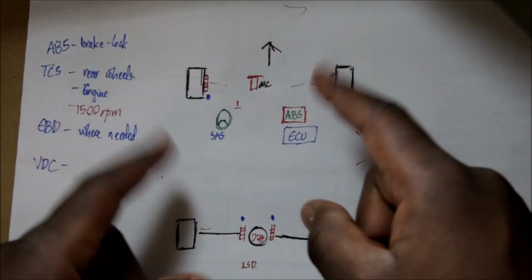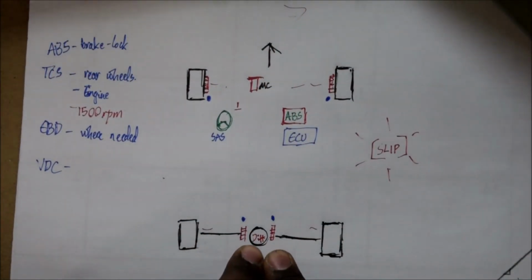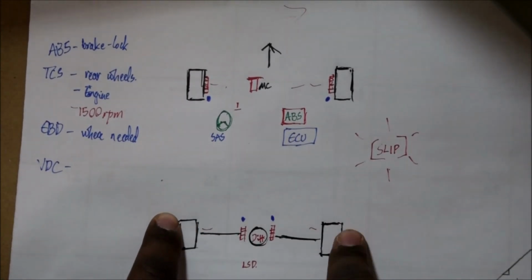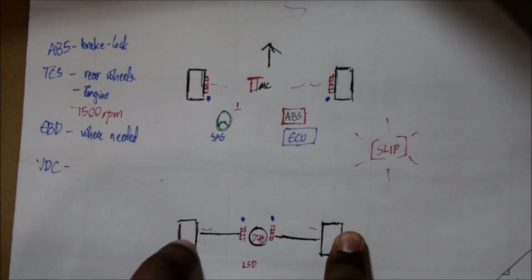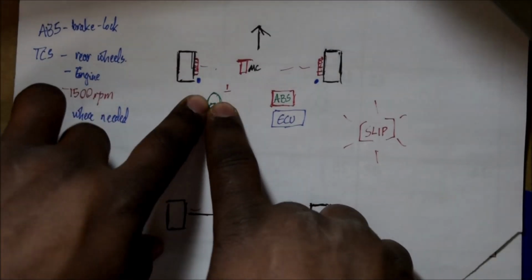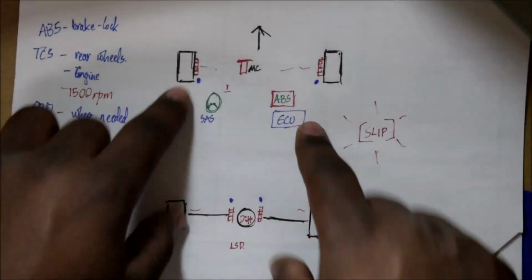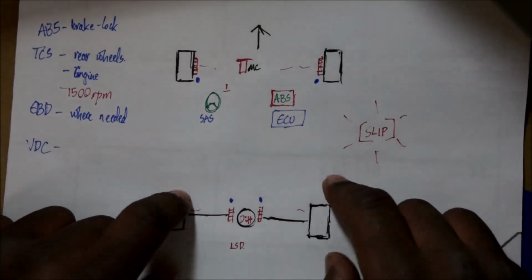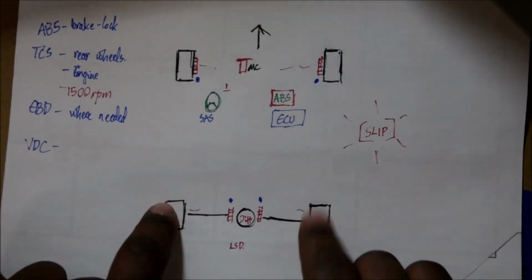If I'm at speed, your limited slip differential wants the wheels to go at the same speed. However, in reality, this one should be slowed down a little bit. What the VDC basically says is, hey, is your steering wheel straight? That means you're trying to go straight. That means we'll try to equalize, not really equalize. We're trying to make sure that you go straight, right?